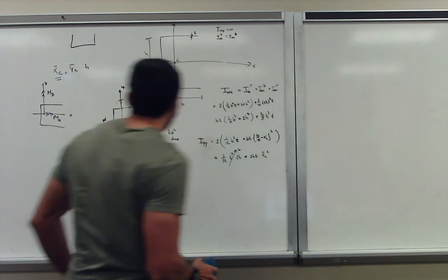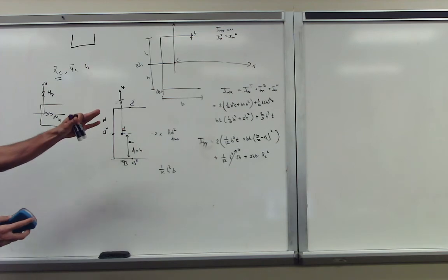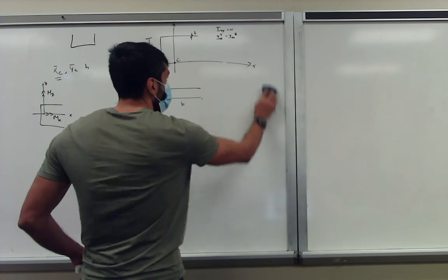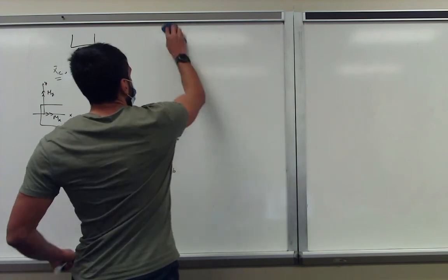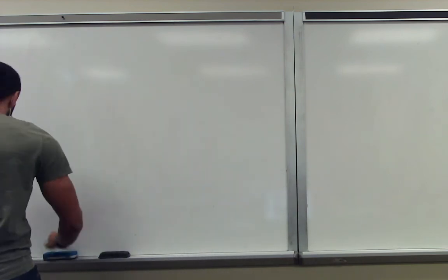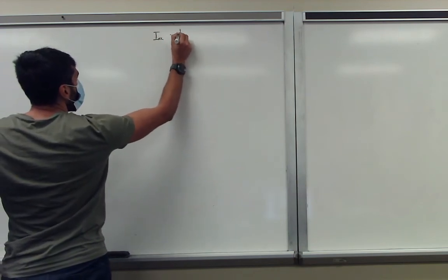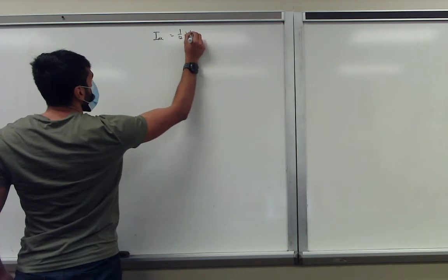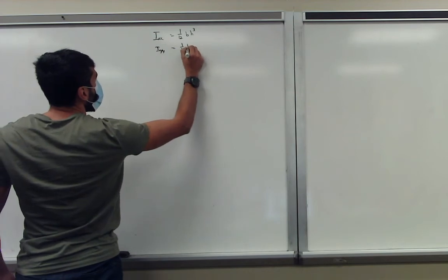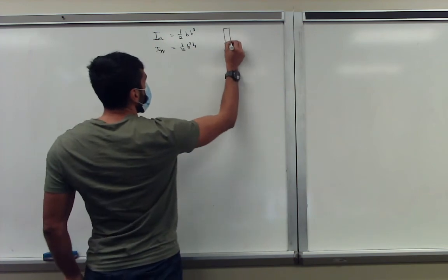About it, you always want to take the simplest way out. So anytime you see a structure where it's basically just straight sections, you can always use the easy, well-known parameters of the moment of inertia, like the formulas. And those two are always good to know by heart: Ixx is 1 over 12 b times h cubed, and Iyy is equal to 1 over 12 b cubed h. Those two are always good to know, and they correspond to something like this.